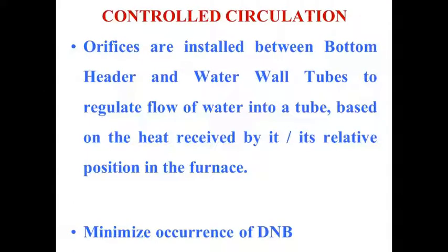By circulation number 1, we mean that the amount of steam generated is equal to the amount of water getting inside the evaporating system. So naturally circulation number 1. That condition only occurs when there is no circulation across the downcomers, and the entire water is converting into steam.